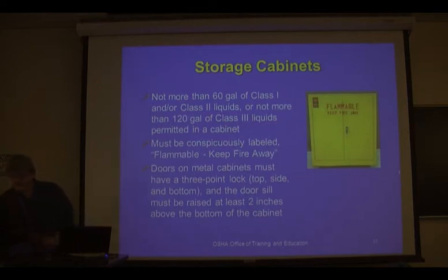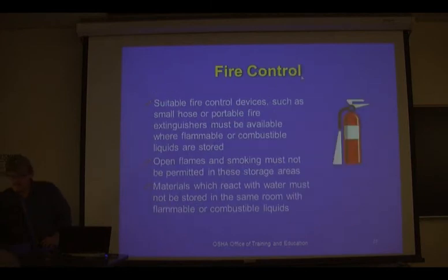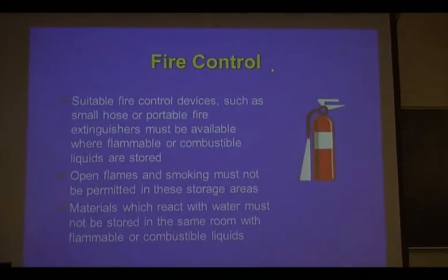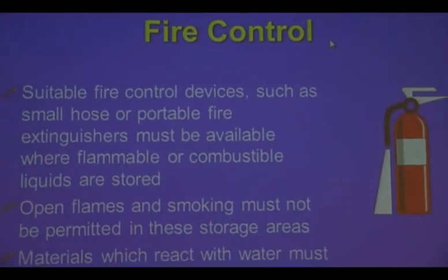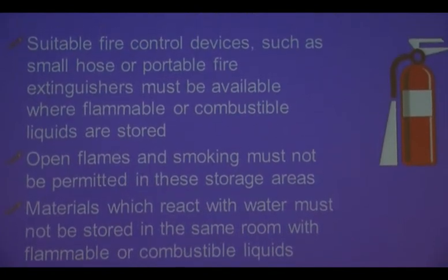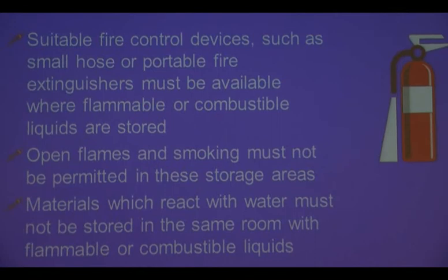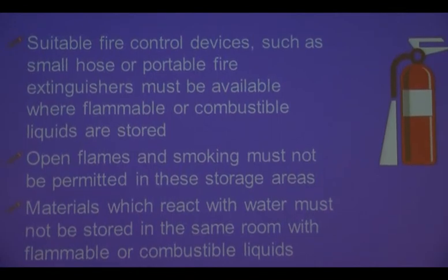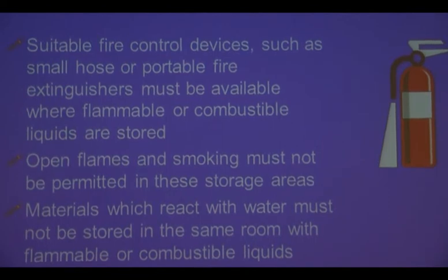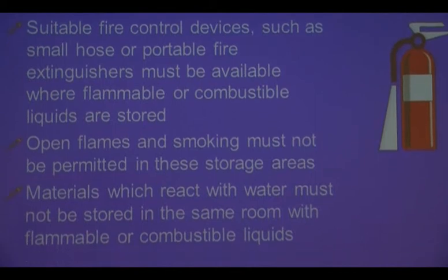So you guys have all seen those. Fire control: suitable fire control devices such as small hoses or portable fire extinguishers must be available where flammable or combustible liquids are stored. No open flames and smoking. Materials which react with water must not be stored in the same room with flammable or combustible liquids. Why? That's right. If you put a fire out, and you have a reactive metal or material that's going to react with water, and use water to put the fire out, then you've got another problem. So don't store them in the same area that has those types of liquids or materials.